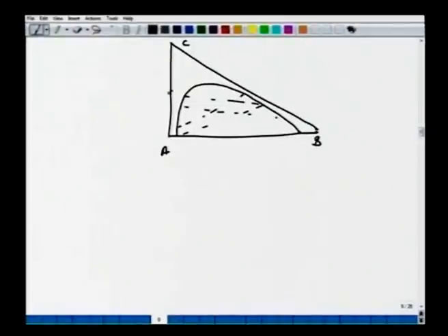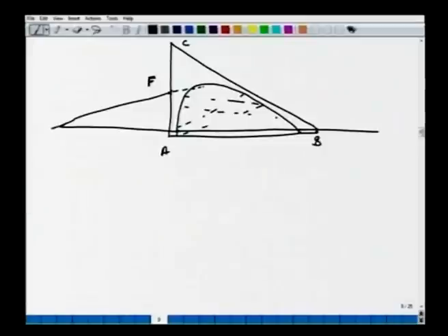We have to find out the amount of solvent which coincides with any of the tie lines, which gives the minimum amount of solvent, and then take 1.2 or 1.5 times to be on the safer side. So here if we fix this RNP and connect this S, this can go either way. To locate this F, find the tie line which you extend to give del min. All right.